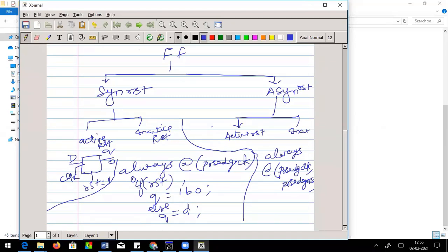Whereas here what happens in asynchronous, irrespective of whether the clock goes from 0 to 1 or it is going from 1 to 0, it doesn't mind anything on that. If you give reset equal to 1, the next moment it makes my output to be 0. That's why we call this asynchronous reset. So if I want to do that, I bring this positive reset or negative reset, whatever you wish. Active, inactive, like that. You can have positive or negative reset also.